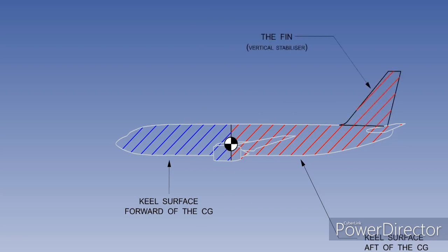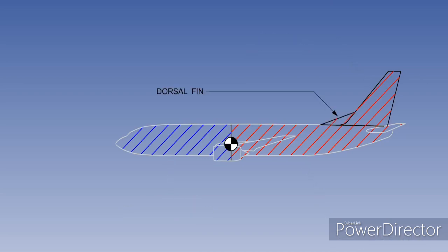We have seen that the fin gives an aircraft directional static stability, but sometimes a basic aircraft design undergoes modification to increase its fuselage capacity, which reduces its static directional stability. It is not possible to just fit a larger fin, so a device called a dorsal fin and/or a ventral fin can be added. These are both lightweight and simple to attach.